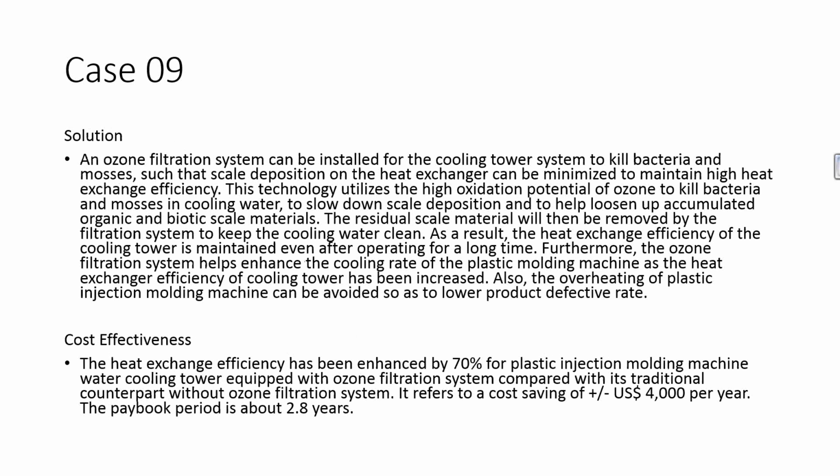The solution for this, an ozone filtration system can be installed for the cooling tower system to kill bacteria and mosses such that scale deposition on the heat exchanger can be minimized to maintain high heat exchange efficiency.